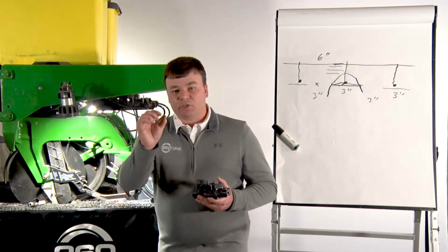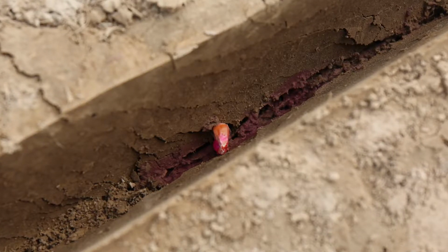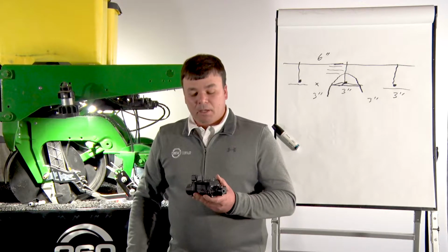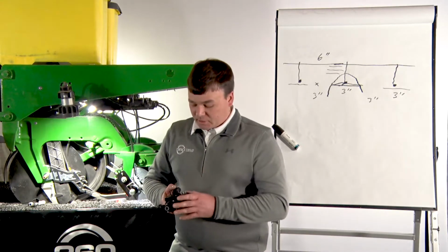We're looking purely for the seed coming down past that seed sensor that starts the whole process for this valve to come to life and apply that dash right over the seed. So the valve itself, we talked about how it works a little bit. It's a needle valve, as I said.